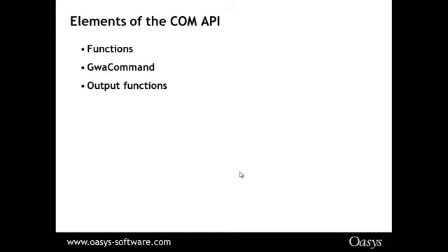Given a keyword, we can find out what syntax it follows, and given an entity, we can find out what keyword it relates to. Using both these pieces of information, we'll need to construct a string that has all the relevant bits of data, and then pass it as an argument to GWA command. We'll go to an example very shortly that will make the usage clear.